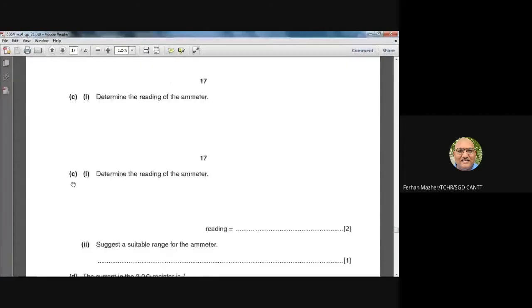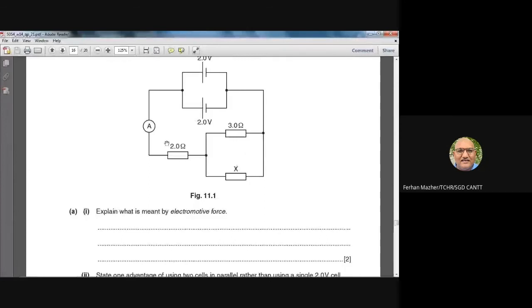You see here we have just calculated that the voltage drop across here will be 1 volt. 2 volt is coming from the battery. So if 1 volt is used here, these two are connected in parallel. It's a conceptual thing. Try to understand this thing. These two are connected in parallel, so both of them will have the same voltage drop. And the total voltage drop will be also the same. Because from the battery 2 volt came, 1 volt was used here. So for this combination, we will have 1 volt. So 1 volt will be used here, 1 volt will be used here. The total voltage drop here will be again 1.